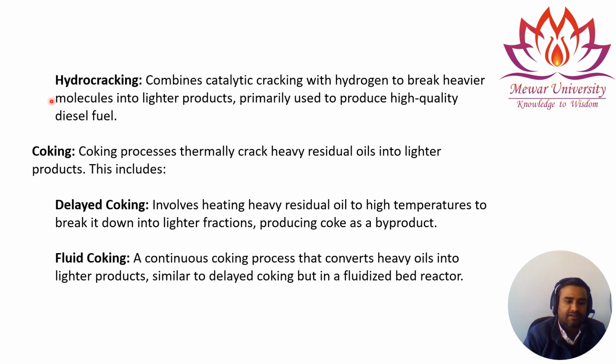This happens at very high temperature, and we are heating the heavier hydrocarbons, which are basically highly viscous and contain long chains of carbon, the distillate obtained from the refinery. At high temperature this hydrocarbon breaks down into lighter fractions, producing coke as a byproduct. Coke is basically your carbon, so that is a byproduct, and the complete hydrocarbon is converted into lighter products which are more valuable in the market.